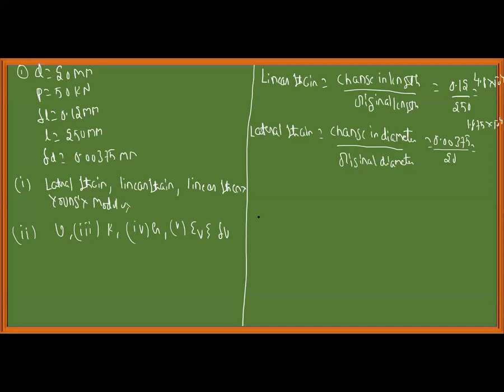Next, he has asked linear stress sigma, which is equal to P by A. The load is 50 kilonewton, 50 into 10 power 3 by pi into area of cross section, circular cross section, 20 square by 4 is equal to...